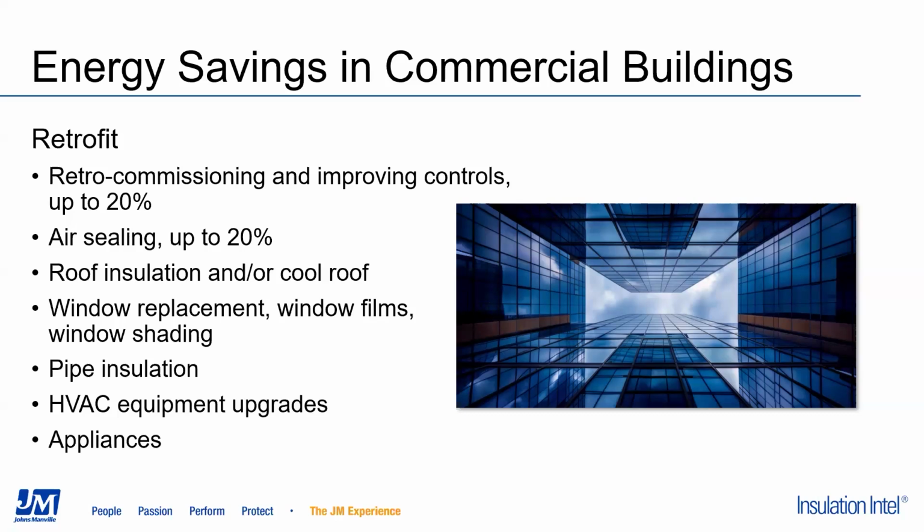And again, this ties back to this issue where so often in commercial buildings we're heating and cooling simultaneously, and that wastes a lot of energy. The more we can reduce how much that happens, the better. Again, air sealing: commercial buildings are notoriously, extremely leaky. The better we can air seal those building envelopes, the better it is.